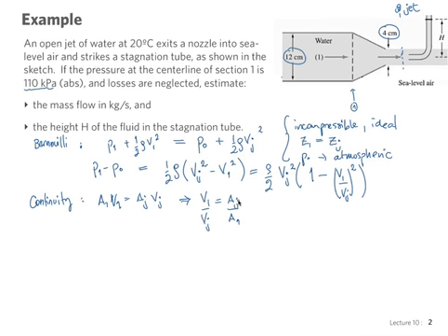And now I can use the diameters almost directly and save me some writing pi's and things. So basically the ratio of the areas is going to be the same as the ratio of the diameters squared, dj over d1 squared.